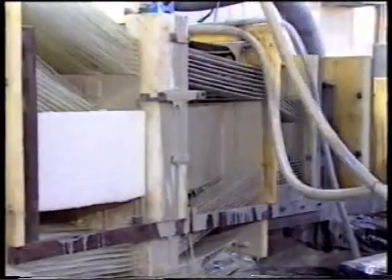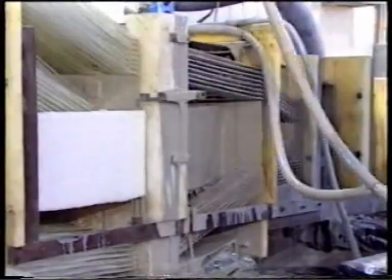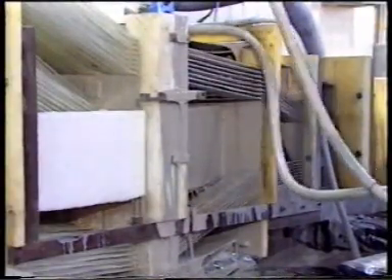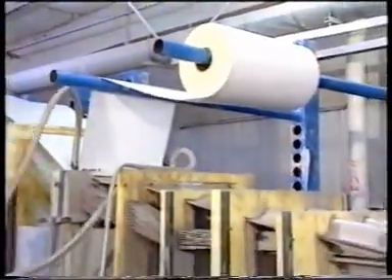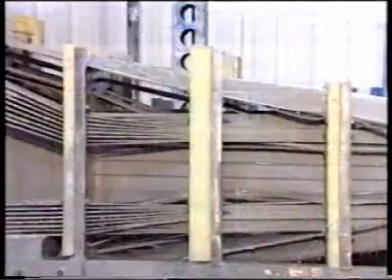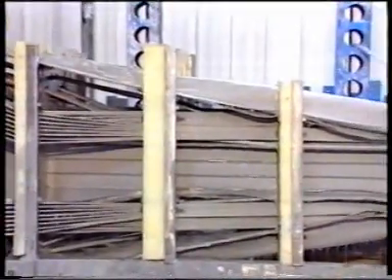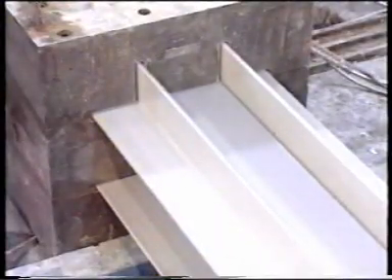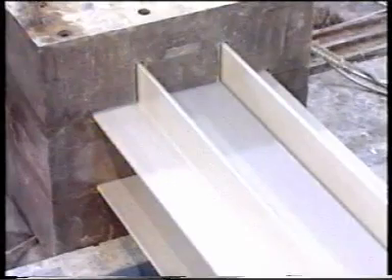The reinforcement is generally resin impregnated by drawing it through a resin wet-out station. A surfacing material is typically added afterwards. The saturated reinforcements are then generally shaped within a guiding or preforming system and subsequently shaped and cured through a preheated die or set of dies. Once cured, the pultrusion is saw cut to length.